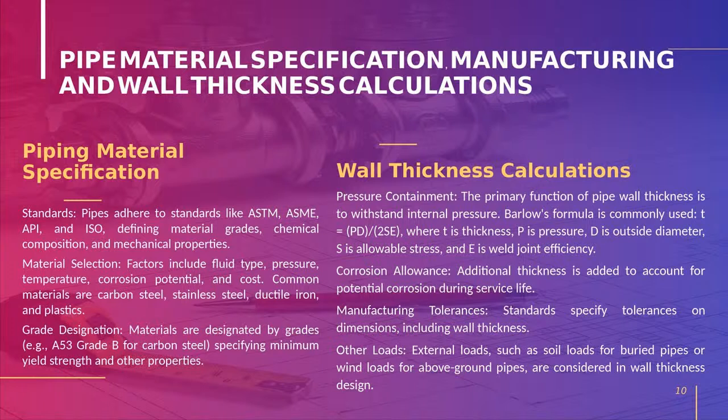Okay, sorry. Wall thickness calculation. We have a manual calculation which is derived from the code book. How we are deriving the calculation, and how we are adjusting the allowances: manufacturing tolerance, corrosion allowance, threading allowance. These are all the allowances which we need to consider while selecting the material. For example, for a steam line we are going to choose a schedule 80 pipe.